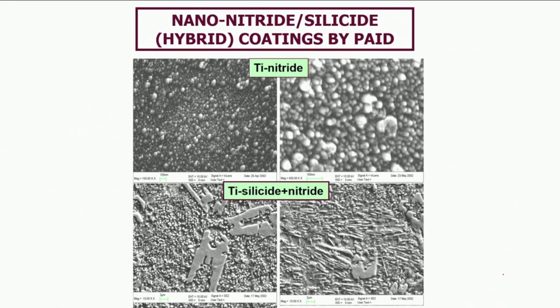In fact, one very bright example I would like to show you is this kind of ultrafine microstructure; this length scale is 100 nanometers. Each of these nitrides that you are seeing, implanted and grown onto the surface, would be about a tenth of that. So typically we are talking about 10 to 20 nanometer nitrides, and you can do it on steel, on titanium, on any other nitride forming substrates.